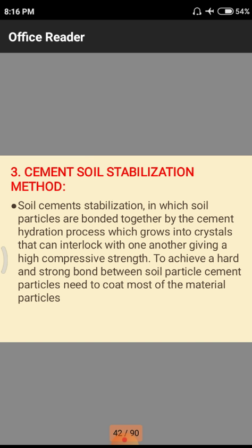Cement has major raw materials of calcareous, siliceous and argillaceous materials, so that whenever these three materials are burnt at 1400 degrees temperature, they will form a clinker. Whenever we cool those clinkers and grind them, they will form a powder.